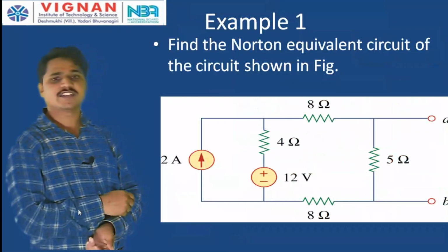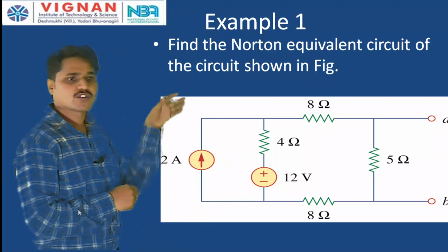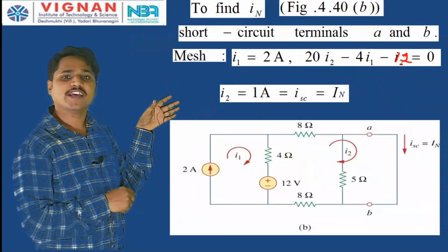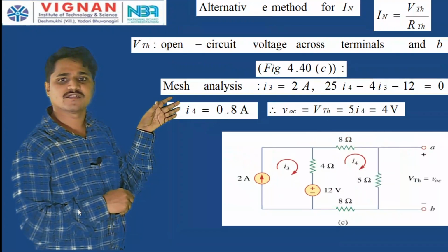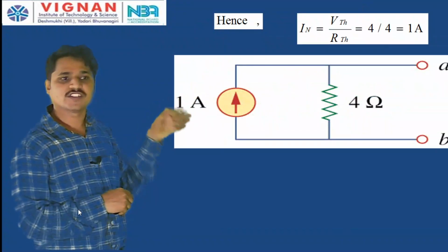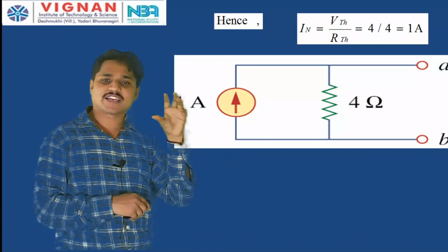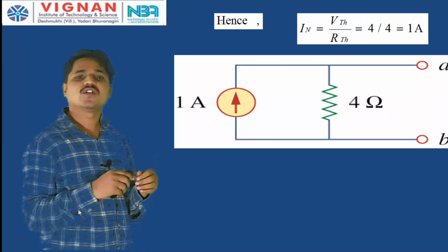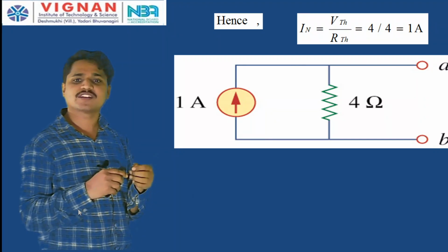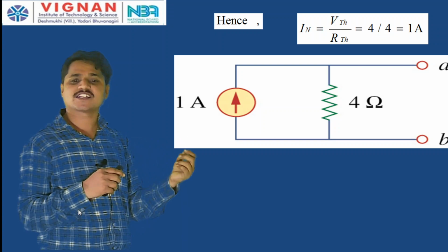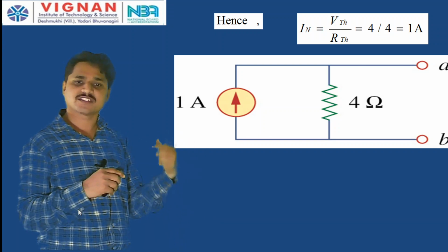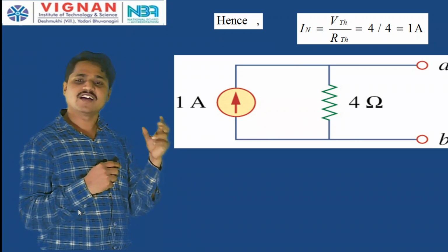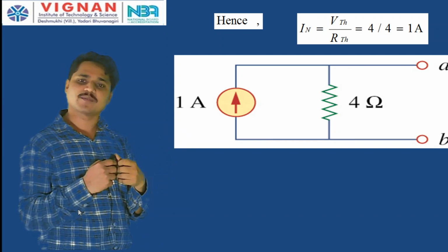Therefore, this is the circuit. Now, this is the given network. So, this given network we are converting into only one network. Now, see, this is what I told you: the given network can be converted into the equivalent network consisting of only one current source in parallel with a resistance. That current we are calling the Norton's current, that is the short circuit current across the same terminals, and that resistance we are calling the Norton resistance, the equivalent resistance seen from the terminals AB.